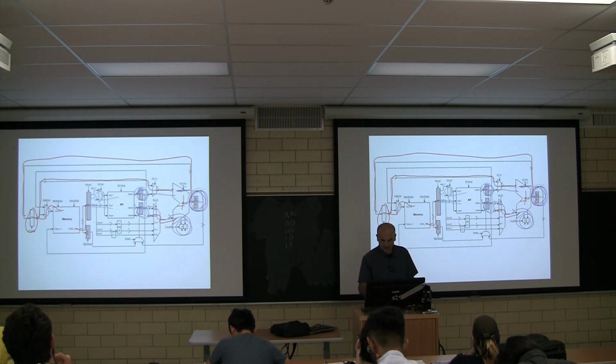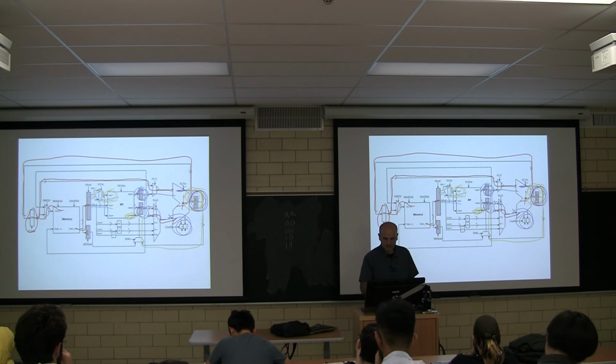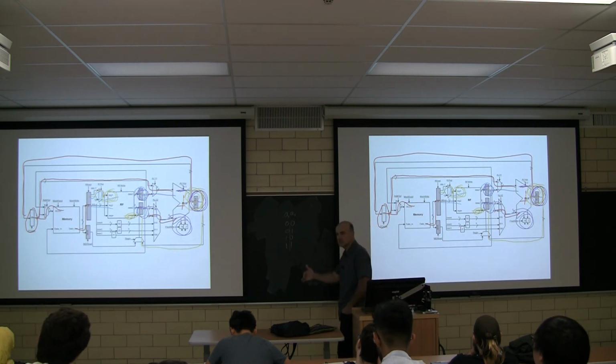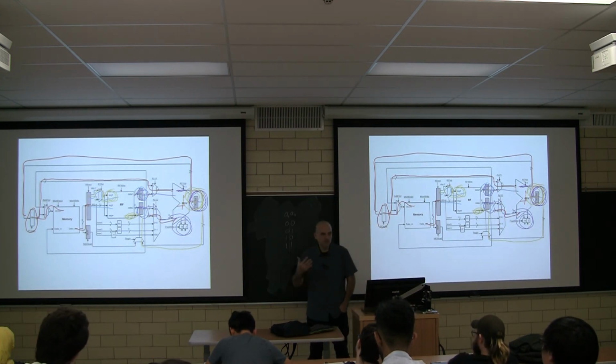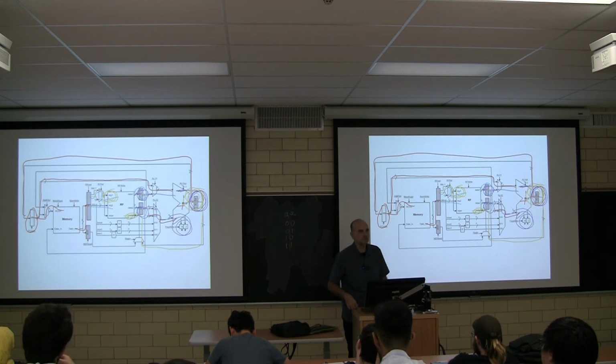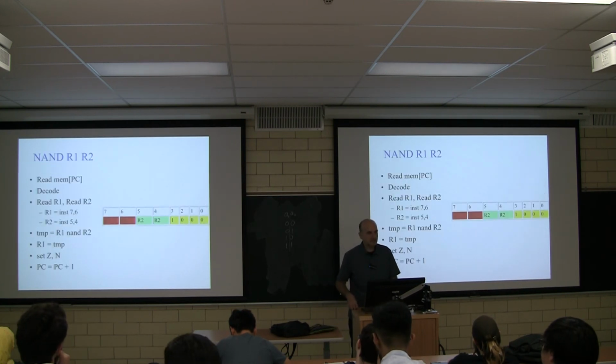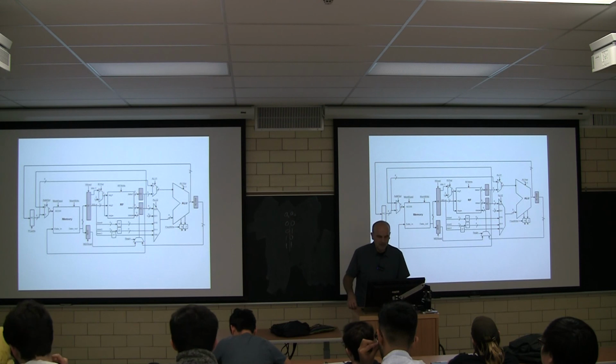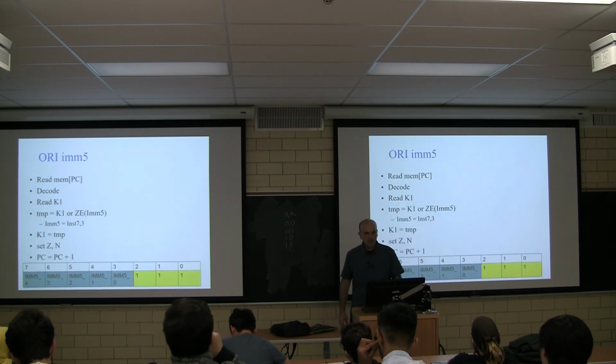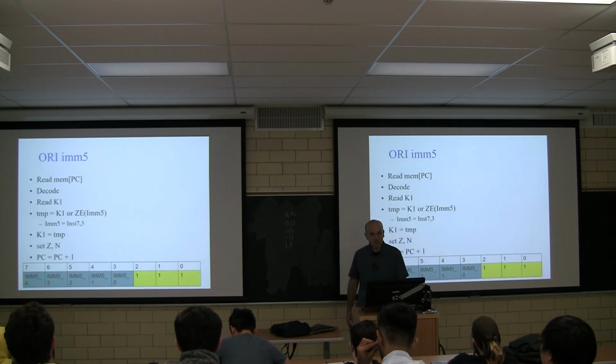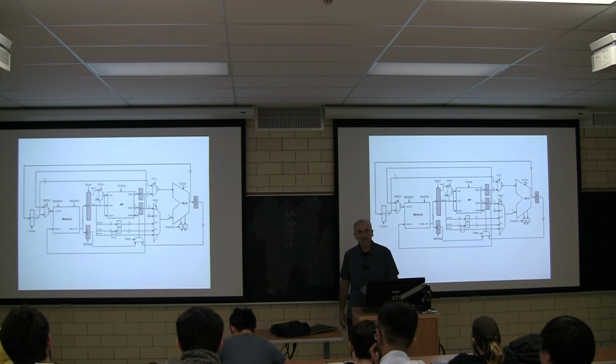We're going to take the result from here and pass it as input to the register file here, and the name from the instruction. Notice that the register name remains stable after cycle 2 onwards, and we're going to write there. Make sense? Okay. Add is identical. Let's do ORI now and understand what's going on with ORI and why ORI is going to make our life miserable.